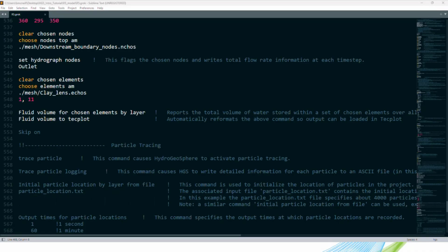It's all aqueous flow. There are commands that allow you to define not solid, but like non-aqueous phase liquids. You can basically set a certain amount of mass that can dissolve into the aqueous phase over time, and it will be treated as basically an immobile store of solute that can just slowly release over time.